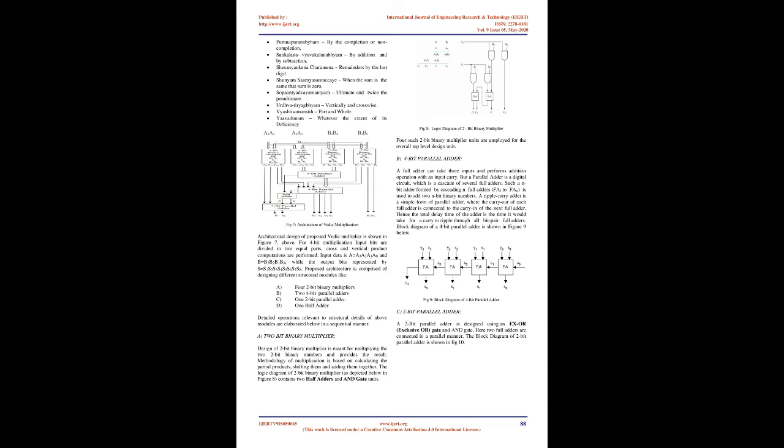Each of the partial products is generated by ascertaining the product of the multiplicand with 1 multiplier bit every time. Likewise, N-1 adders are required, where N denotes the number of multiplier bits, to complete the process. Hence the array multiplier is considered to consume more logic gates and hence occupy more area. Therefore, the array multiplier is economically less feasible, though it is faster in operation. The architecture for array multiplication is shown in Fig 5. Fig 5, example for array multiplication.